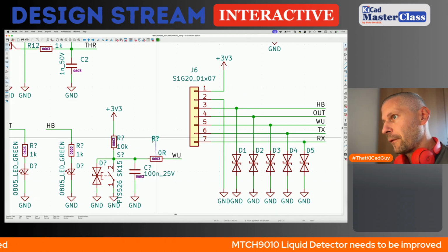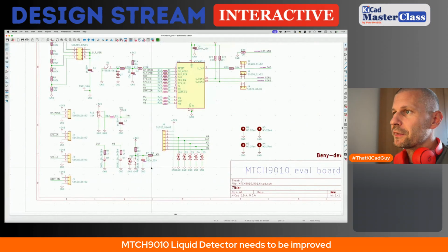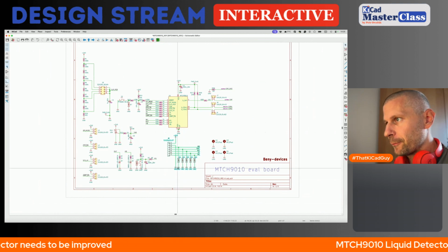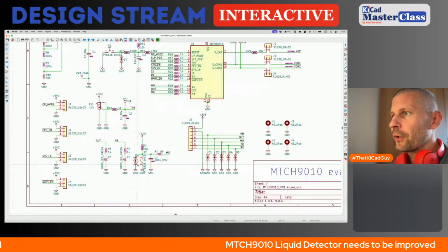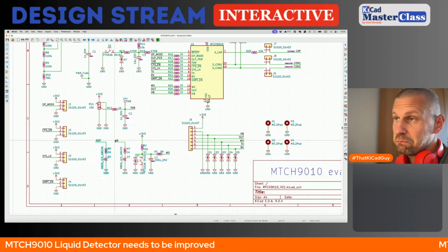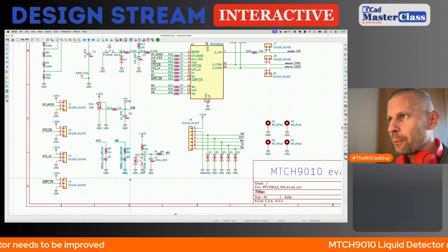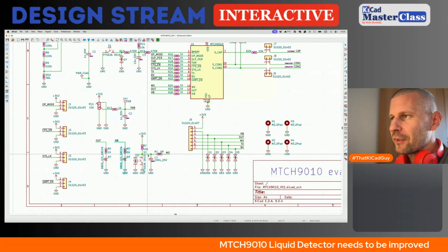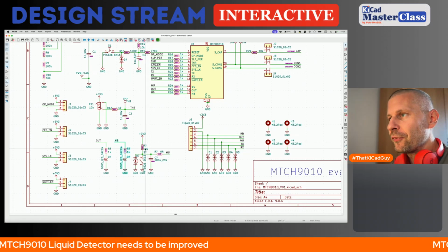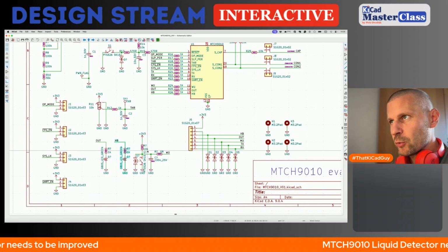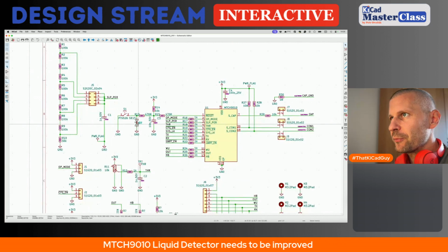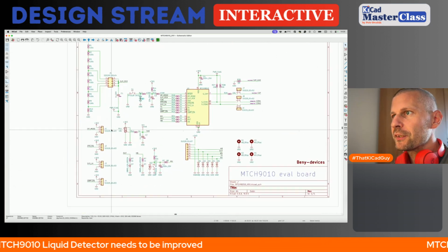Okay. So I think it's bulletproof now. We can disconnect the button circuit. It's ESD protected. We have monitored out pin, heartbeat output pin, and we can generate negative or falling edge events, plus as well when the button is released, we can generate the rising events as well. So the reset port is ESD protected as well. We don't need to protect this.